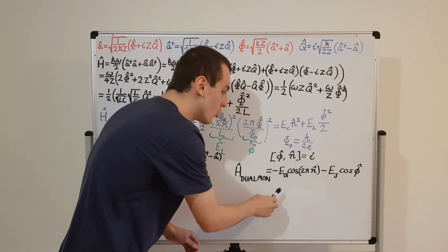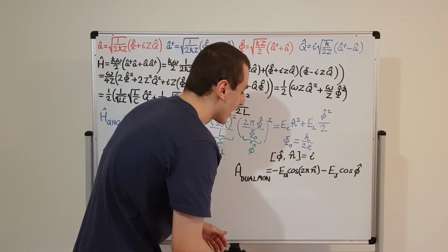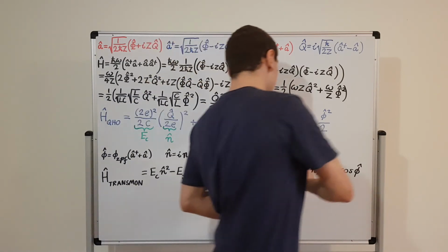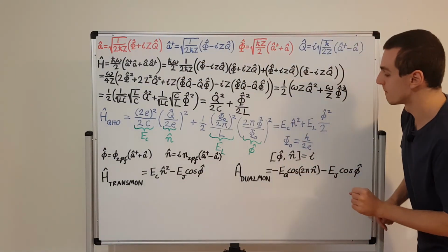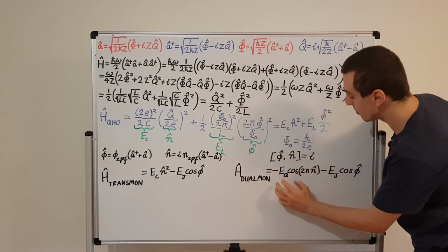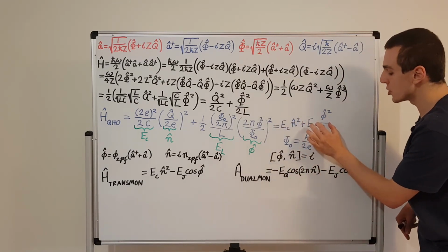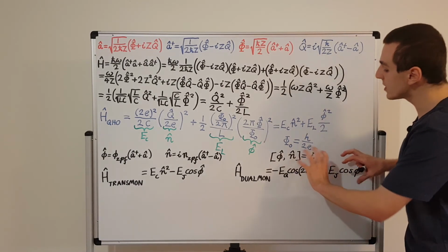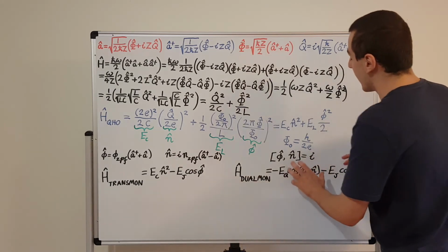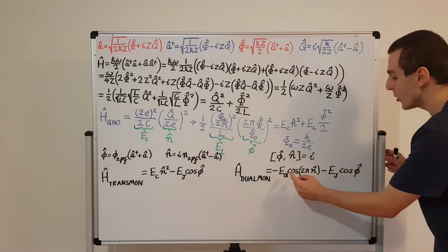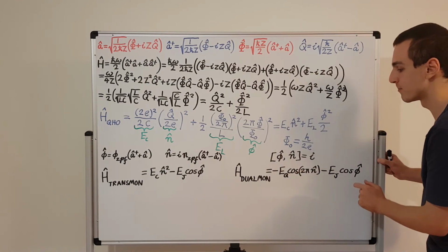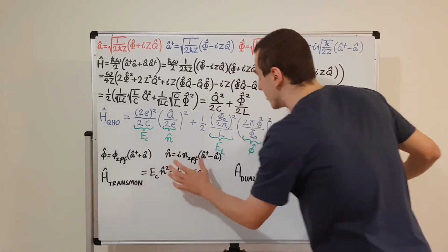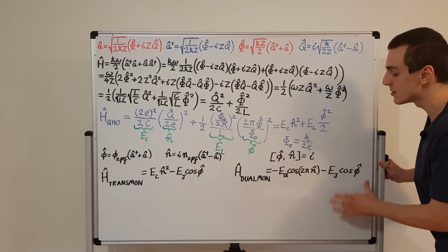So this EQ is referring to a QPS, a quantum phase slip. This is another type of device. So this device is actually analogous to the capacitor. So the capacitor has turned into this QPS, and the inductor has turned into a Josephson junction. That's what this J stands for. So these are just different types of devices, and they have excellent properties. They have these very interesting nonlinear dependences over here. So this is the Hamiltonian for the Dualmon, and this is the Hamiltonian for the transmon. These Hamiltonians have applications in quantum computing.